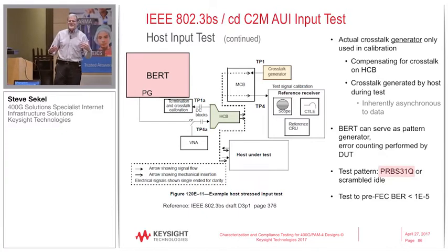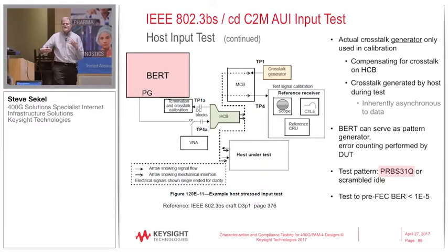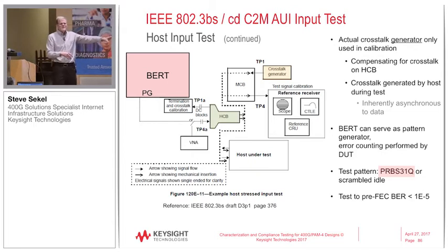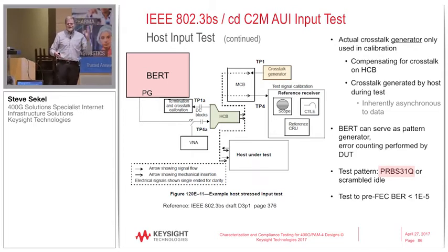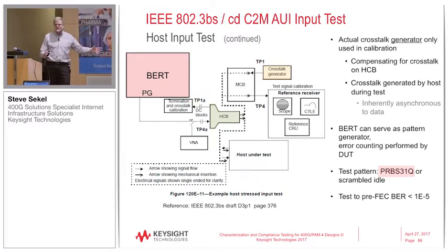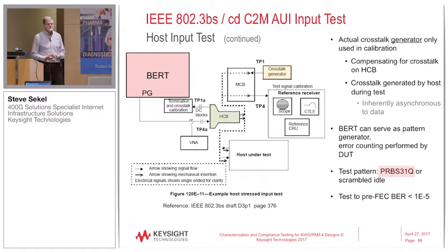And you do find in cases where some of the first generation chips, or some of the chips that do have serial loopback, that the error counter in the chip reads a better BER number than the error detector on the BERT does. And again, this is all in a PAM4 environment, and that's attributable to the transmitter having distorting mechanisms in it that are not perfect. So the standards are always measuring perfect BER.